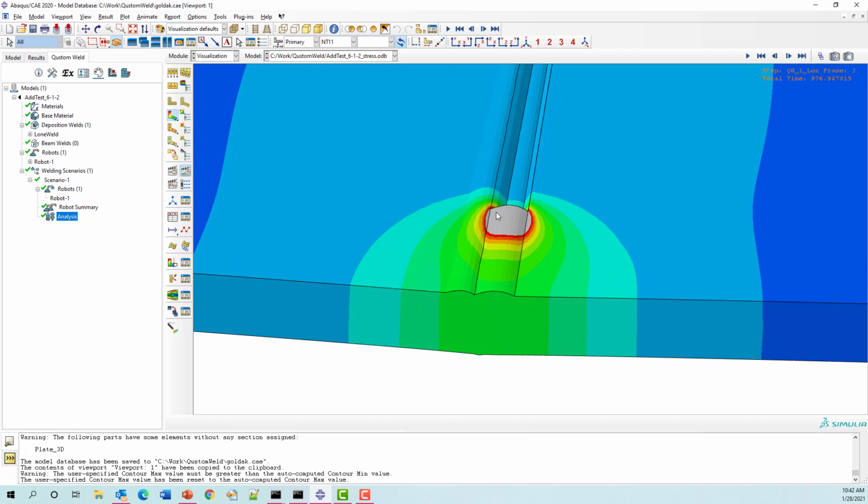So when the elements are activated in the stress model, they're activated at melt temperature. Now these gradients are going to be away from melt temperature. So the initial condition, the initial temperature that's used in Abaqus, is actually the melt. And then there's a delta T for every element. So there's a strain that's calculated from that. So it works out well the way Abaqus does it.